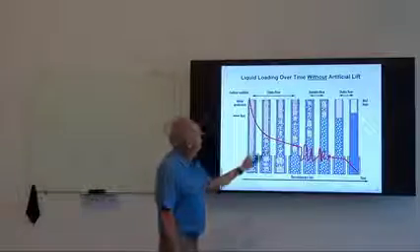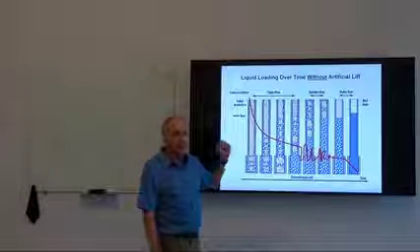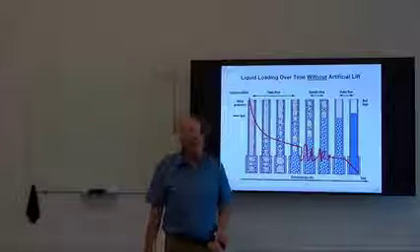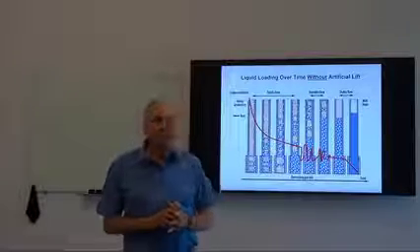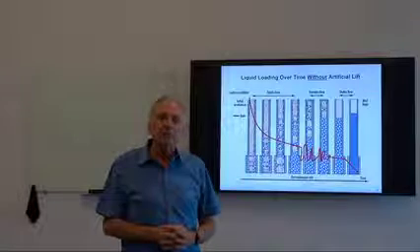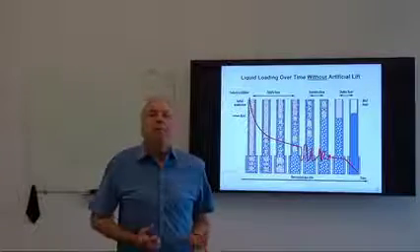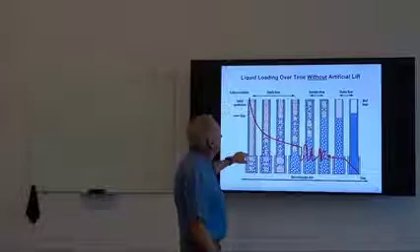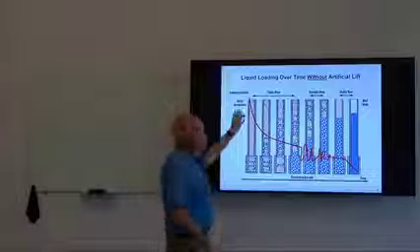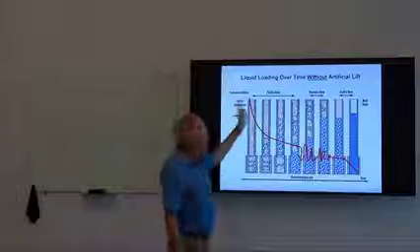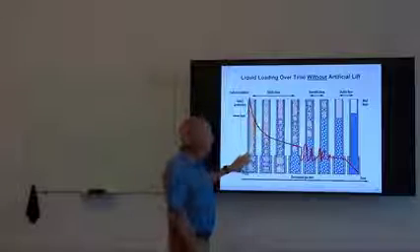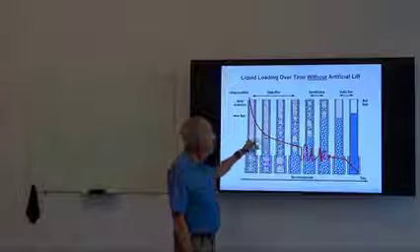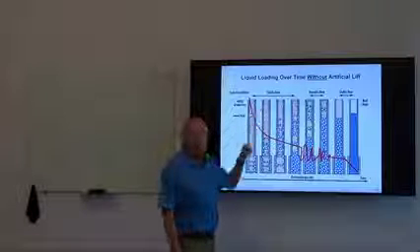So in natural flow, now we talk about artificial lift, but in natural lift or in natural free flow, the well is evacuating all the liquid out of the wellbore by virtue of the velocity of the gas. So think of it as a wind blowing up a pipe. If that wind is blowing strong enough up that pipe, then it will take that liquid up and out of the well. But of course our wells deplete over time, and as that production rate falls off, bottom hole pressure is dropping as we deplete pressure out of the reservoir. Rates drop off, and we start to see accumulation of liquid.